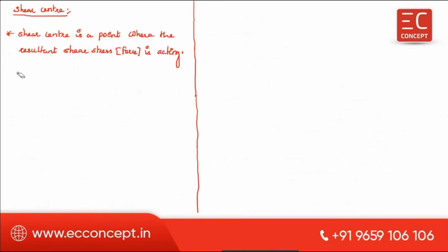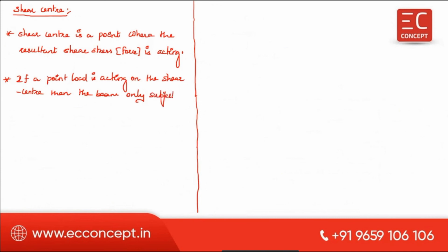Next one is, if a point load is acting on the shear center, then the beam is only subjected to pure bending moment and no torque and no twisting. So these two are the important points.